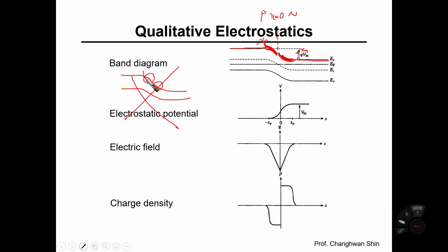You should split it into 1, 2, 3, 4, four different regions, and you should draw four different segments, and then just connect the four different curves together. Then you're going to get the conduction band edge E sub C for the Pn diode.